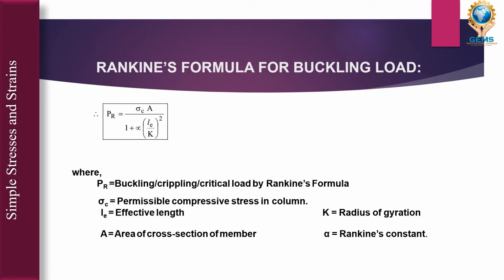So this is the formula for Rankine's buckling load. You have to keep these things also in your mind. Once again I will repeat it: P_R is equal to sigma_C into A divided by 1 plus alpha times (L_E by K) whole square.